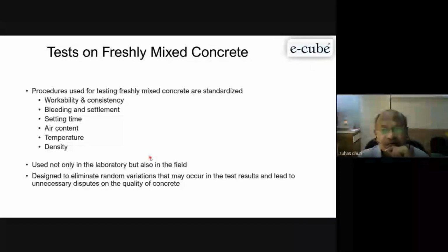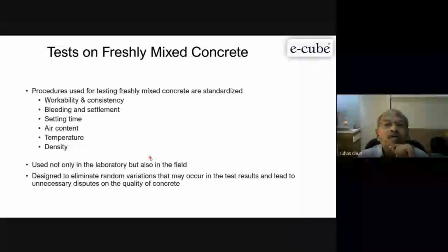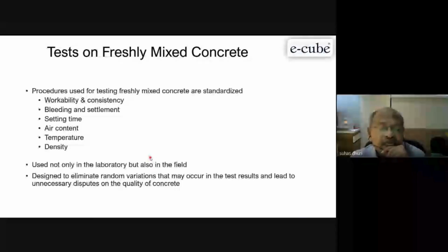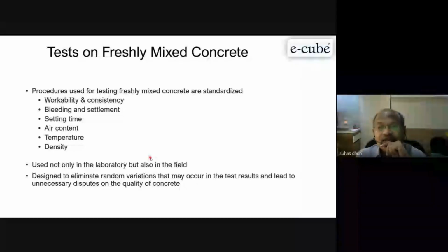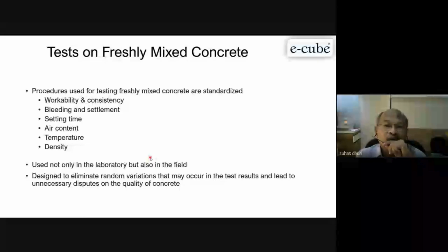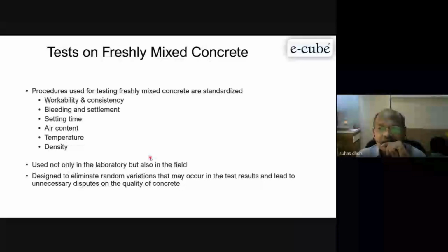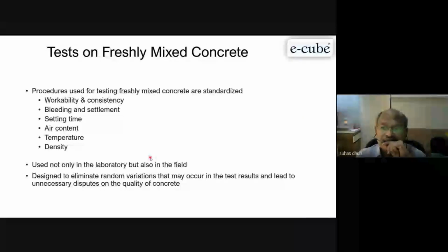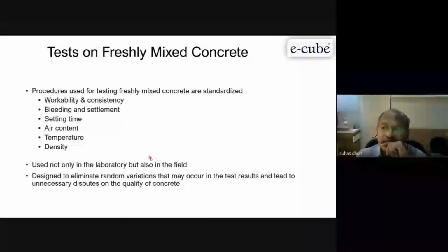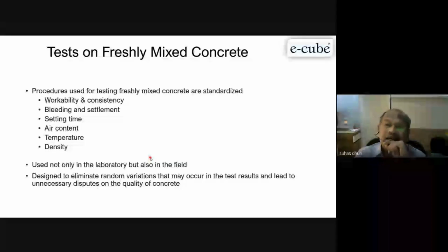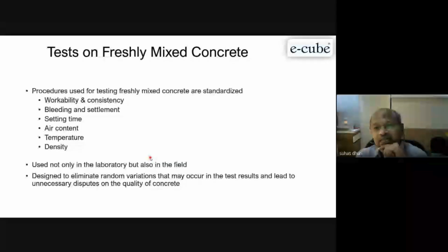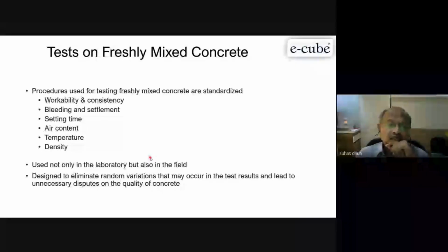So here the concrete mix design plays a major role in selecting the proper cementitious system to reduce the temperature at the core. That is one. Secondly, your placing temperature has to be low, not the normal temperature like 32, 33 degrees. No, it's not acceptable. It should not be more than about 28 degrees. Still, below is always better. Now how to come out of that? There are standard procedures and standard practices people are using, and that also we'll discuss during our mix design process.